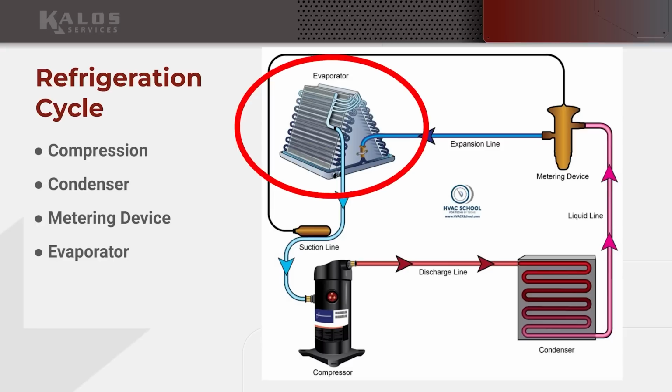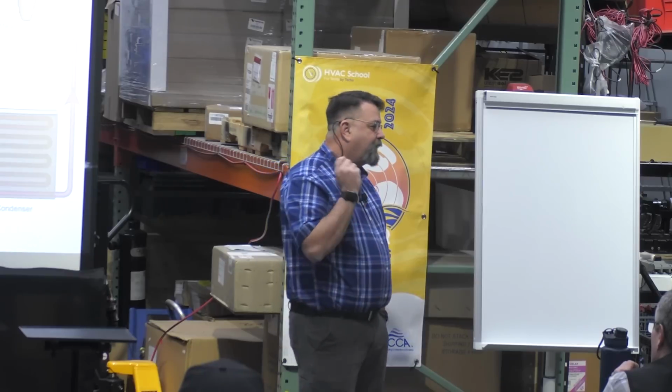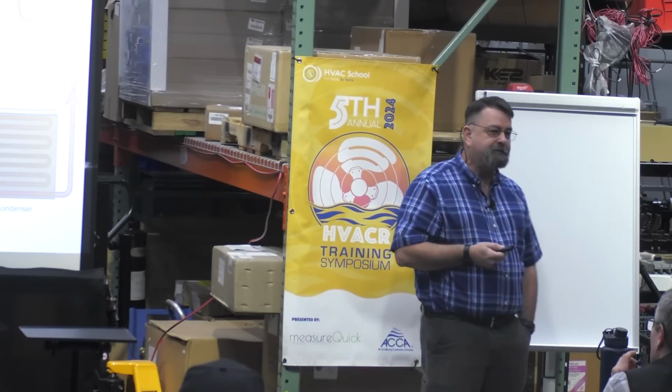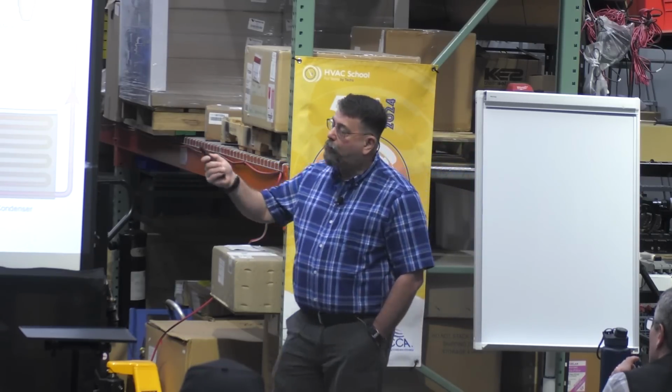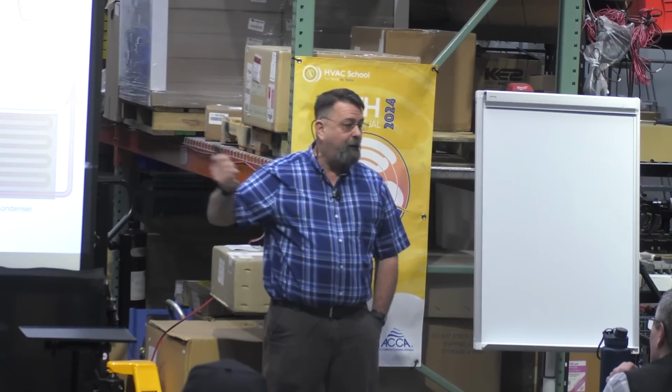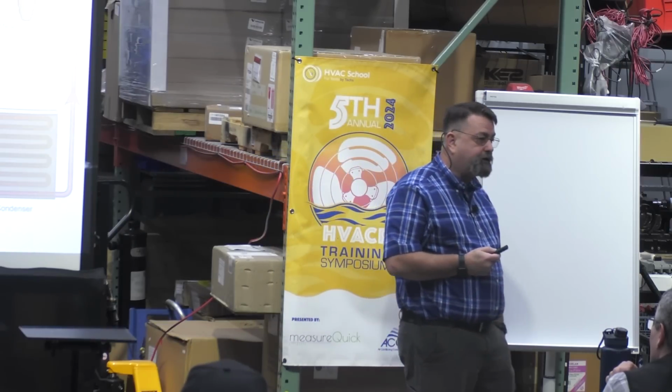So the reason that it is, and what we're going to do about that, is because of our PT chart, right? I just talked about saturation, right? When we're at saturation, we equal our PT chart. Well, inside my evaporator, I got vapor and liquid, right? I'm at saturation. That means I can control the temperature of that evaporator by controlling my pressure directly.